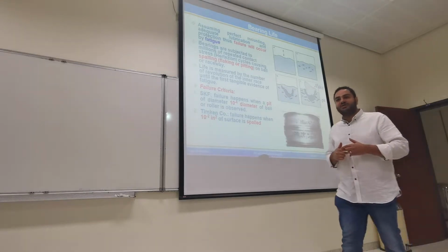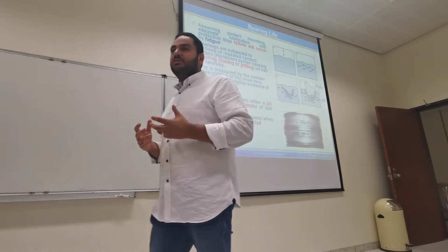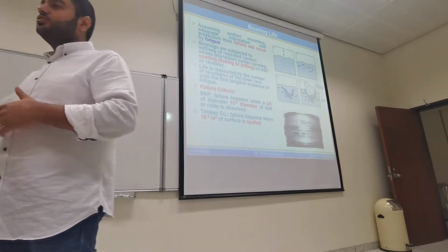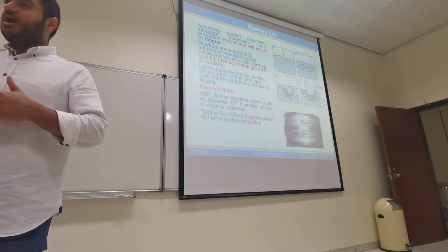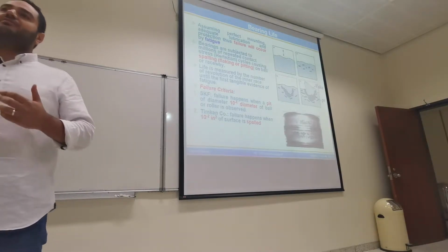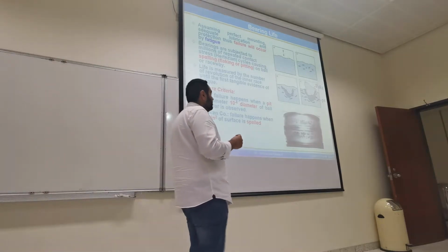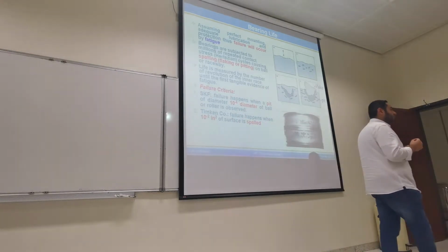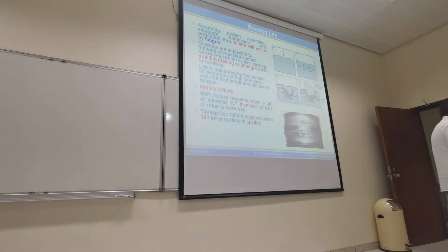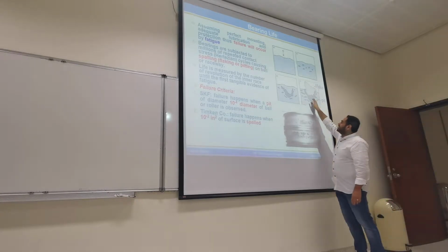So we know the fatigue is when the material is under cyclic load, right? When the stresses fluctuate, compression, tension, and the load is changing with time, we have what we call a fatigue phenomenon. What happens in fatigue is that the small defects inside the material, there is no material without defects, form cracks, and these cracks will start to propagate, and eventually we'll have separation.